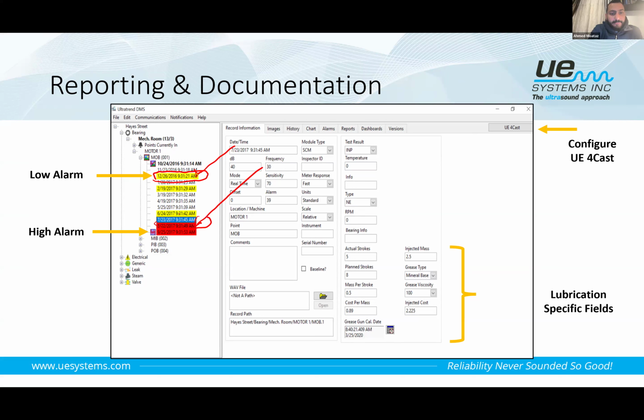This is a predictive alarm. So now 8 decibel above the baseline means that I just need to lubricate the bearing. 16 and above, now I need to recheck this bearing, record the sound for this bearing, and make some analysis for this bearing.